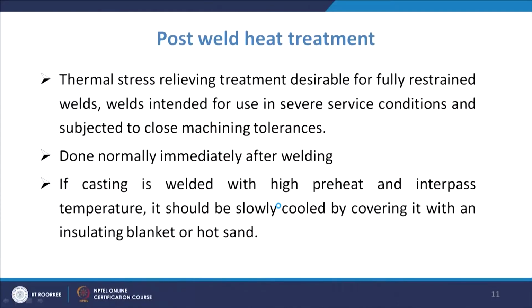Then we also go for post weld heat treatment, and thermal stress relieving heat treatment is desirable, especially for fully restrained welds, and wherever these components are to be used where there is close machining tolerance, you have to have the stress relieving treatment as a necessity.